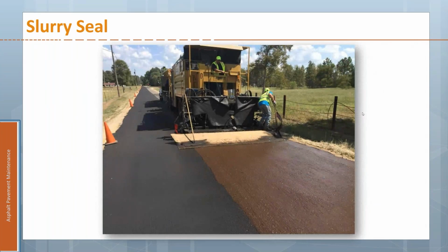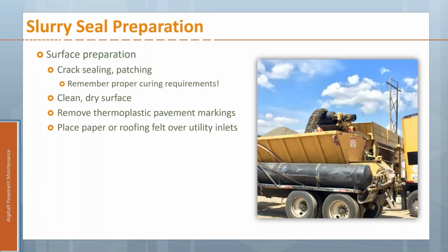So all the materials get mixed together in this hopper, and then everything gets pushed to the back, and it's not really like a paver, but a little bit. Everything is mixed together, and then an auger spreads it out, and then you've got this burlap drag that sort of smears it onto the surface. I don't know if smears is a nice technical term, but that's kind of how that works.